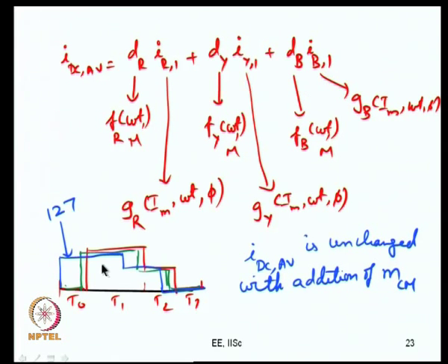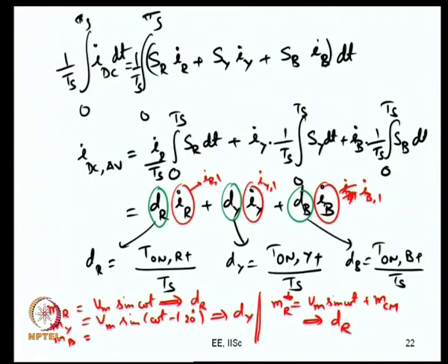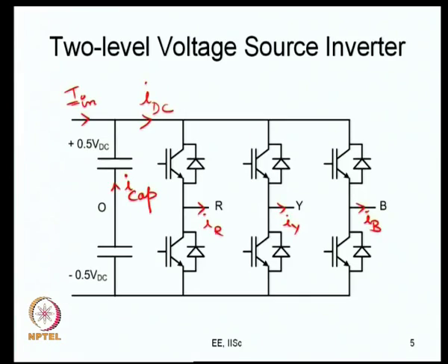So, today what we have tried to do is get a feel for this problem and how we can relate the DC link currents and the AC side currents. We have primarily got that now, and what remains to be done is to come up with this I cap. For this, we need to get a clear expression for IDC, and once you have this IDC average, you can get a further average of this IDC over the sector, that is its periodicity, and that will give you the DC current. This DC current flows from the supply, and we can assume the rest of the ripple to be flowing from here now.